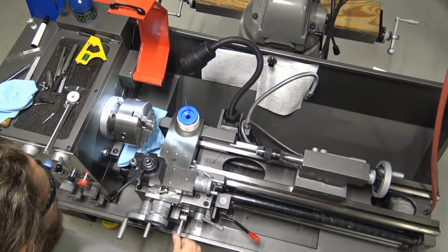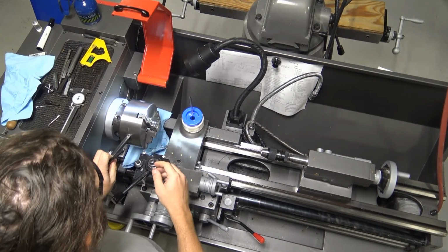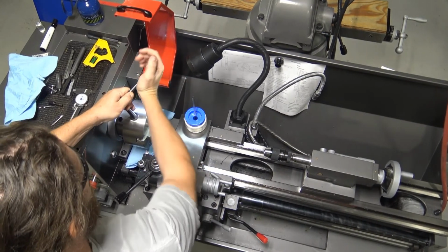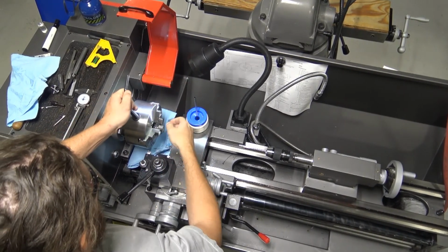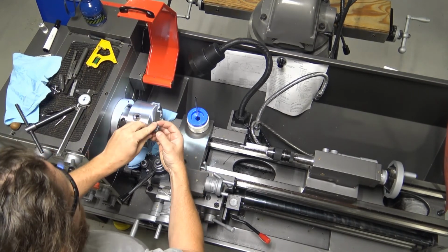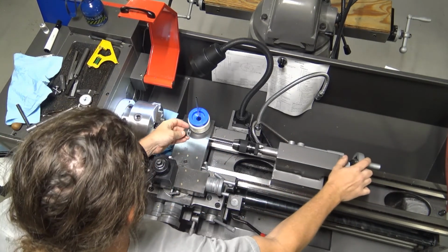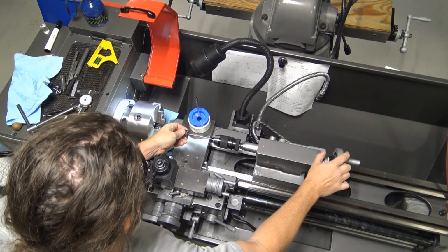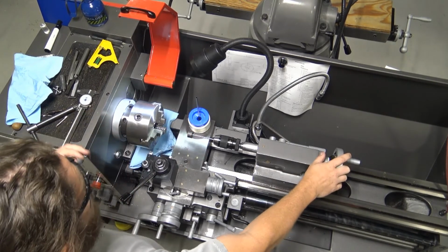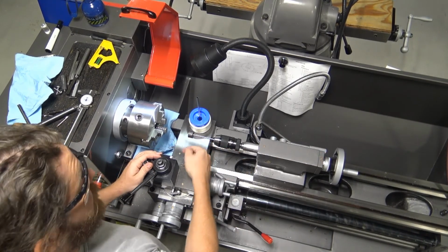All right, so now we're going to go to flipping it around. Remember, anytime you take something out of the chuck, it's never going to go back in the same way it came out. All right, so when we turn this around, what we're going to want to do is mount it on this reamer, because that is right at the center. That's the hole that we just reamed, and if I mount it on there, it's going to keep this hole right in line with the center of rotation.